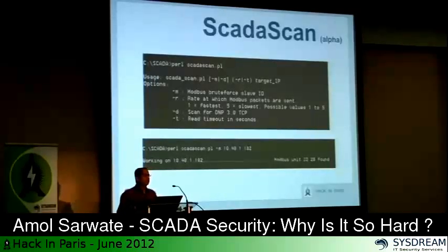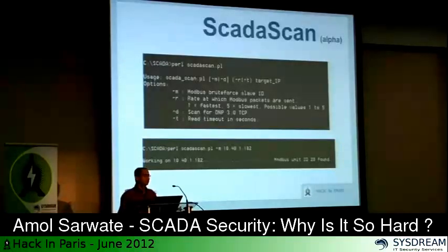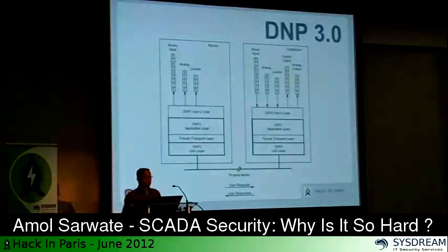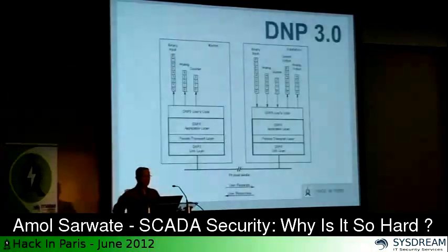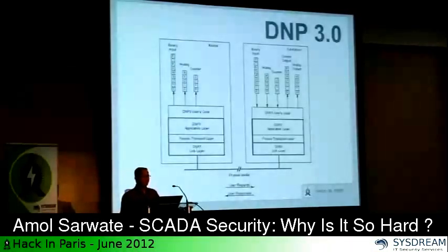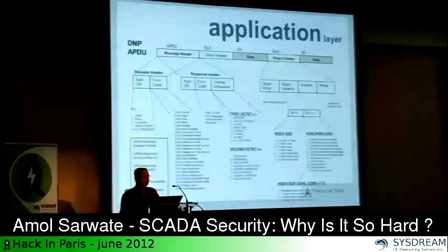So we said, okay, DNP3, it's a newer protocol designed from the ground up. It has these 3 layers, and again, we are not going to go into a lot of details about this, but it has a link layer, a transport layer, application layer. And the application frame looks like this. Again, not going into too much detail, but it looks sort of similar.